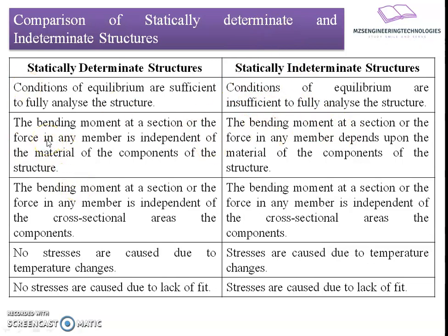The second point says the bending moment at any section or the member force in any member is independent of the material of the components of the structure. But in a statically indeterminate structure, we use the material properties to find the constitutive relationship so as to find the unknown forces, like we have done in the strain energy concept, where we used material constants like axial rigidity, modulus of rigidity, and many more, with the material constant E, the elastic modulus, in the equation to solve for the unknown forces.